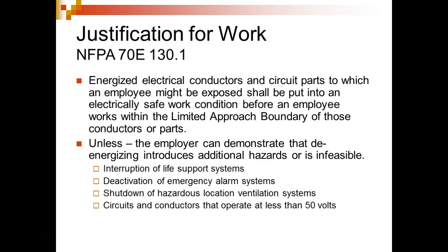If you put it on ohms and you put it in a circuit, when you put it on ohms, it becomes an actual voltage source or a current source. So you're pushing current back through something that's trying to put out current. That could turn into a big problem, right? You could blow up your meter, or you could have other problems.